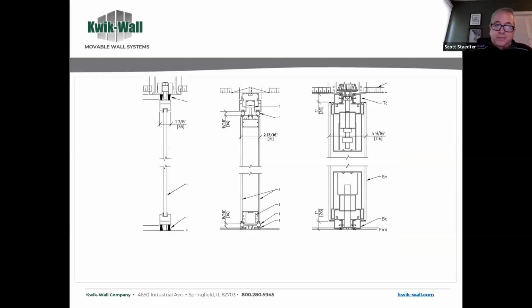And then you have a frame around it and flanking paths with sweep seals and so forth. It's going to perform at that 32 level. Now you go up here and you do two pieces of glass, but to combine that glass is a quarter inch, it's a half inch, it's the same amount of glass, but you separate that and seal that in place, that airspace of 2.5 inches. That really drives acoustics. So you're going to go from like a 32, in this case, up to a 43 STC, 43, 44.